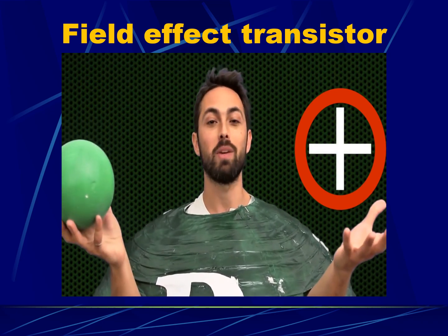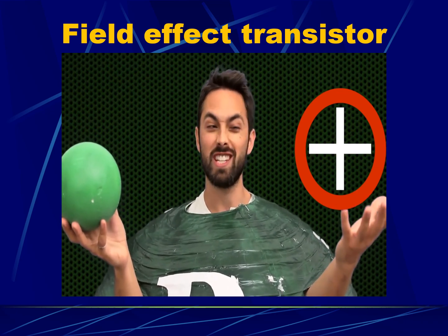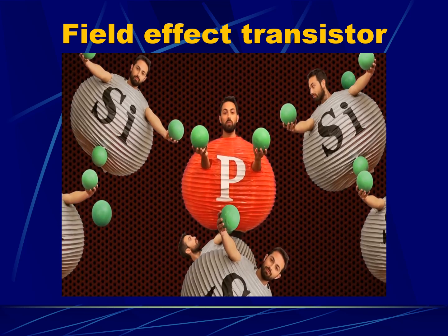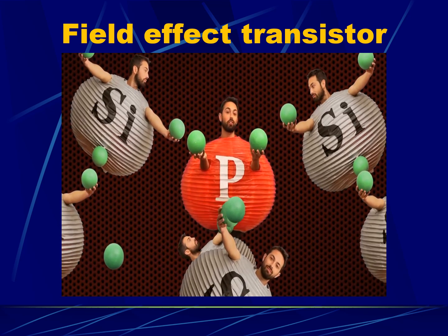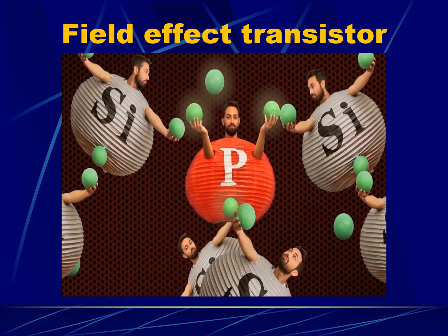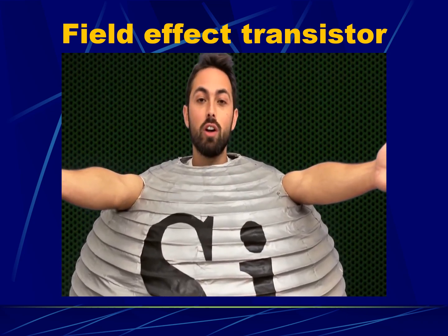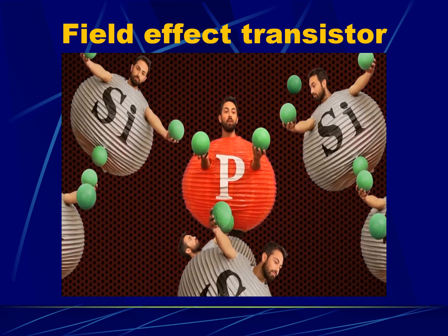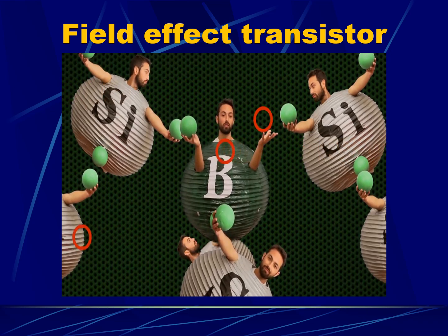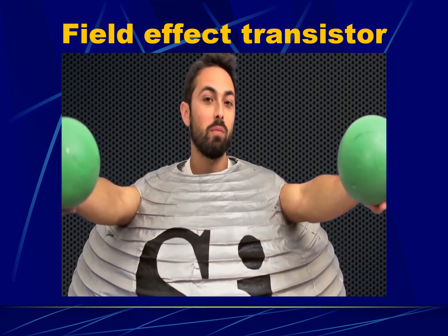And this is why P-type semiconductor is actually called P-type. The P stands for positive. It's positive charges, these holes, which are moving and conducting the current. Now, it's a common misconception that N-type semiconductors are negatively charged and P-type semiconductors are positively charged. That's not true. They are both neutral because they have the same number of electrons and protons inside them. The N and the P actually just refer to the sign of charge that can move within them. So in N-type, it's negative electrons which can move, and in P-type, it's a positive hole that moves. But they're both neutral.